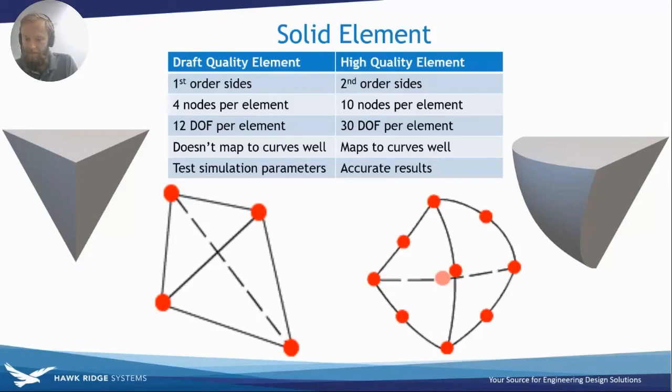No, the weld itself lines on the drawing. So if it's not modeled in the CAD geometry, it's not going to have solid elements attributed to it inside of simulation. However, inside of simulation, you can use a connector to simulate different welds.